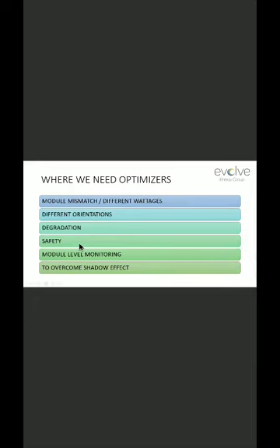And safety. Safety is the main criterion when you are installing a solar power plant. Imagine you are installing a solar power plant. If it is a three-phase system on a rooftop, it is about 1000 volts of DC string you are installing on a roof. If there is any leakage or any fire accident, what safety have you given to the DC side of the plant? You have given anti-islanding protection for your AC side, that is a mandatory thing. What safety condition have you given for the DC side? Nothing. The answer is nothing.